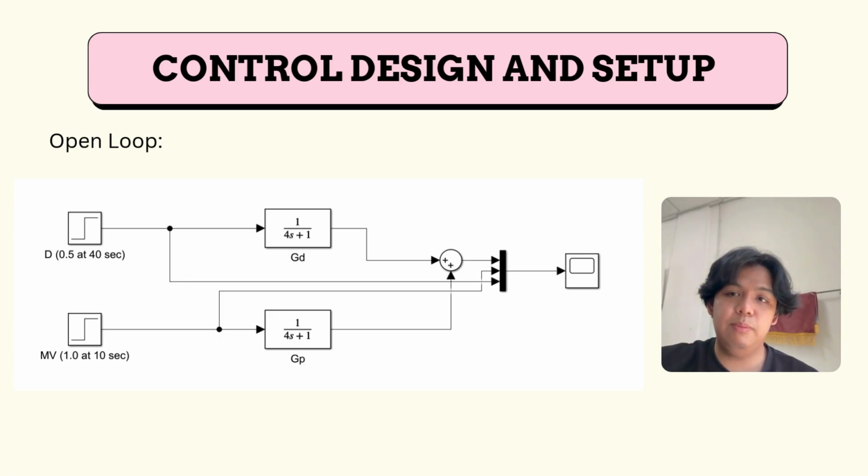This simulation helped me to observe the natural response of the process without feedback, understand how the process responds to both input and disturbance, and use the oscillation behavior to determine the ultimate gain Ku and ultimate period Pu when testing under proportional only control in open loop.